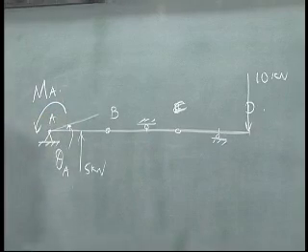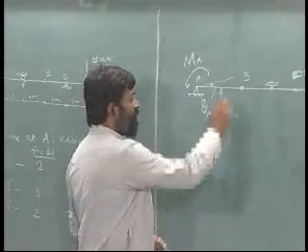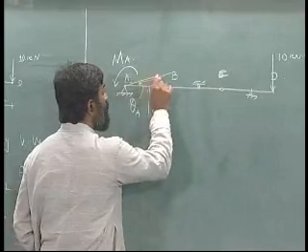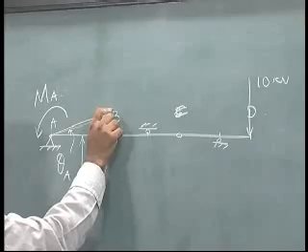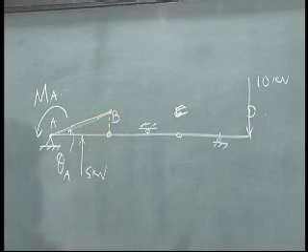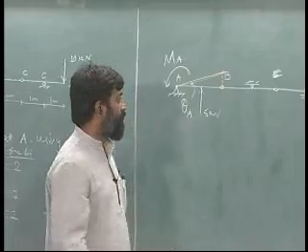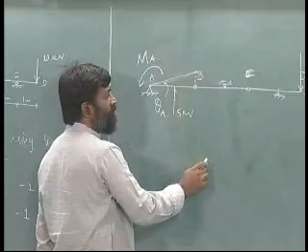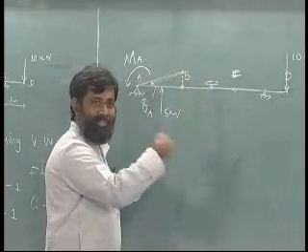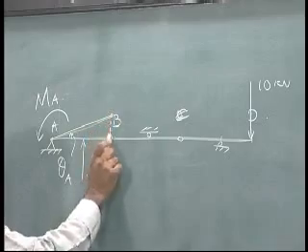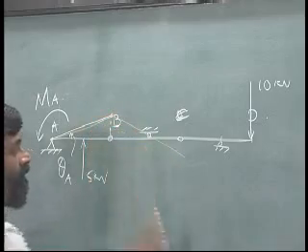And if I am rotating like this, what should happen to B? B will start to move up, right. I am just using the simple geometry. So, let me draw with some other color. It would have moved by this. Okay. How do I find out the displacement at B? That is not very difficult. This rotation times the length will automatically give me the displacement. Once this point has moved to this, we are left with the similar concept that we used earlier. This point cannot move. The only way that this displacement can occur is by movement like this.